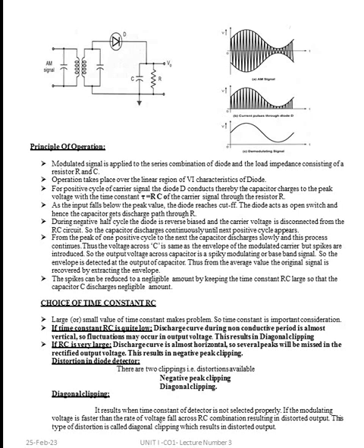The spikes can be reduced by keeping the time constant RC value large. Then the capacitor discharges a negligible amount, and we reduce the spike amount. Then we have to choose the RC value in a proper way so that we can reduce the distortion. So a large or small value of time constant makes problems. So the time constant is an important consideration.